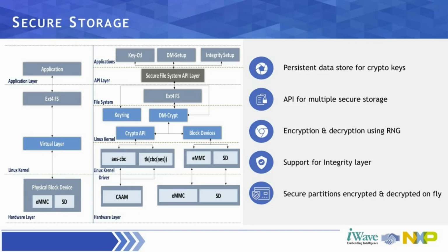The keyring enables these interfaces to allow access to the keys and perform operations such as add, update, and delete from the user space. The CAAM is instructed to use a black key as an encryption key. The CAAM automatically decrypts the black key and places it directly into a key register before using the decrypted value in the user-specified cryptographic operation.